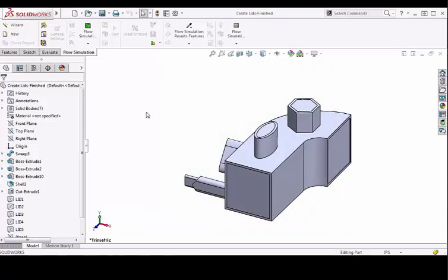the Check Geometry tool. The main purpose of the Check Geometry tool is to inspect the model for invalid contacts, such as a line or edge contact, and also to calculate the internal fluid volume within the SOLIDWORKS model. Before running the simulation, your models must be checked by flow to make sure they can be meshed and solved for correctly, and also to ensure that there aren't any problems with the geometry that might prevent meshing.